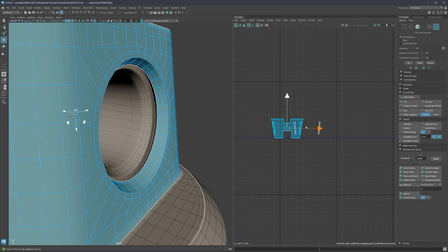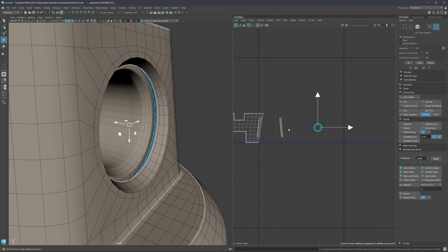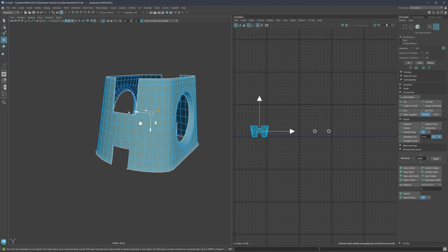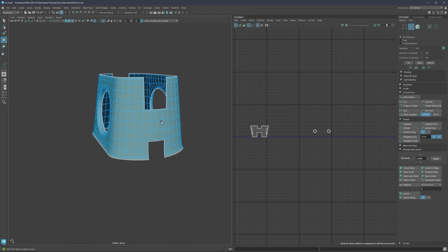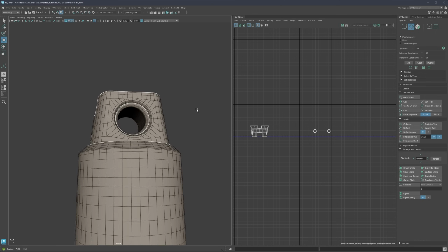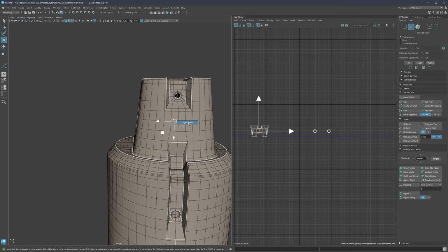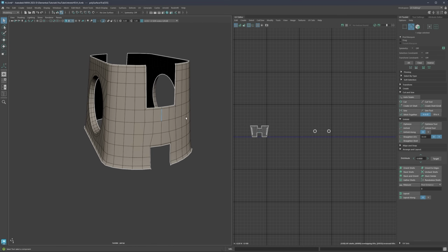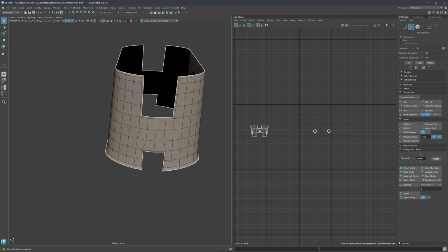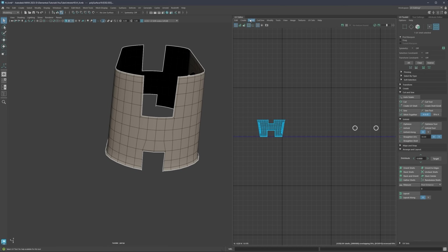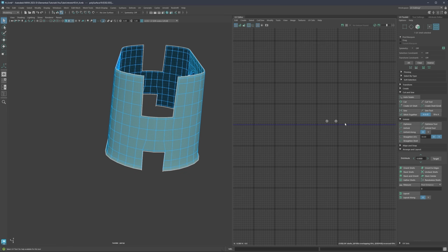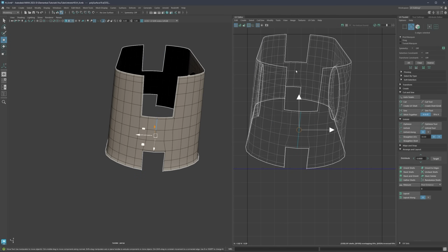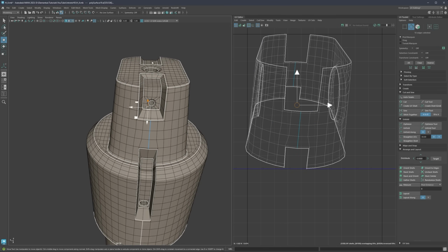And I think now you're slowly getting to understand what is the whole process here. And it's very straightforward. The only thing is it might be slightly time consuming. And the same thing, let's now find a nice place for a seam, and it's going to be these two places. So the easiest is just going to be to create camera-based UVs here. So select the shell, create camera-based, push it to the side, and now we can easily from here select the cuts. So we don't have to worry about selecting the whole loop.